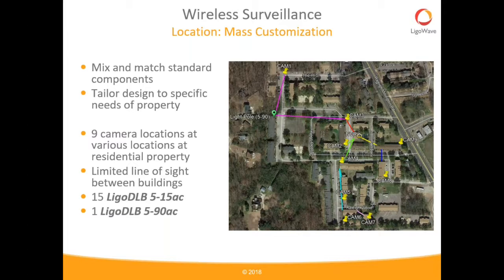In this case, along the purple link, pretty much all of your video traffic is flowing from cam 1 to that light pole and then out again towards cam 3. Then it can take a secondary link back to your main distribution frame where your network video recorder is located. And that's perfectly fine. That saves you some additional equipment and having to worry about additional links.